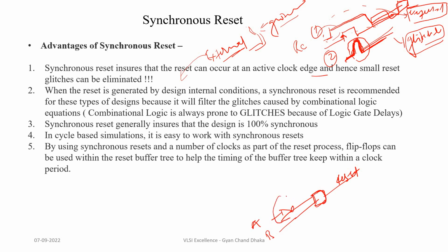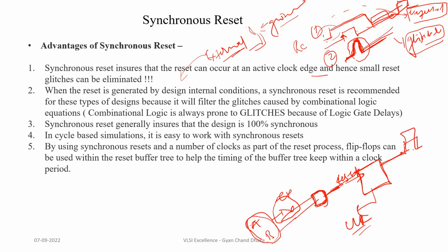Because of the delay inserted here, both A and B signals are not getting asserted at the same time, and we can have a glitch at the output of the AND gate. So by registering this signal with a flip-flop, we make sure that the reset gets synchronized with the clock domain, and then we do not have any kind of glitch here, and this reset signal can go to all of our design's real flip-flops.